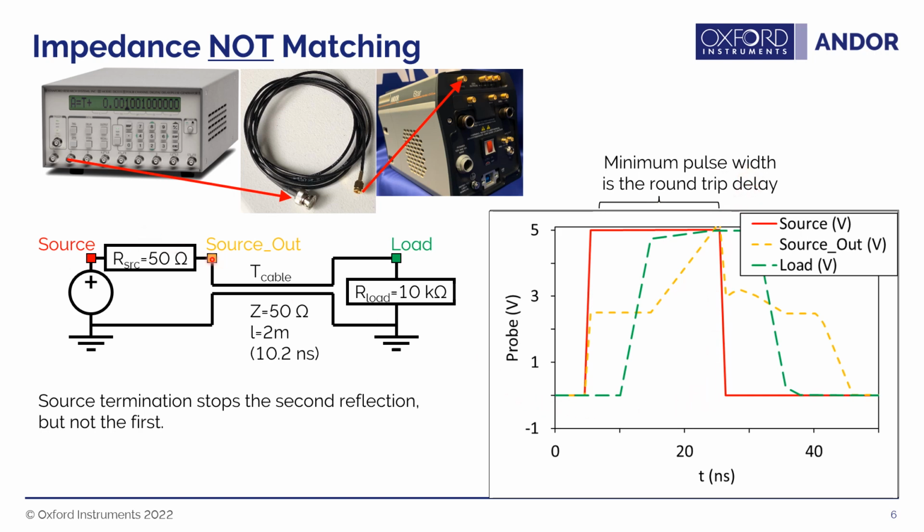And so then you can see that because there is the ringing back and forth in this circuit, you see this jump in voltage coming through. And finally, at the load, since it's a high impedance, you see the voltage is actually higher, but it's a little bit not as steep as it could be.